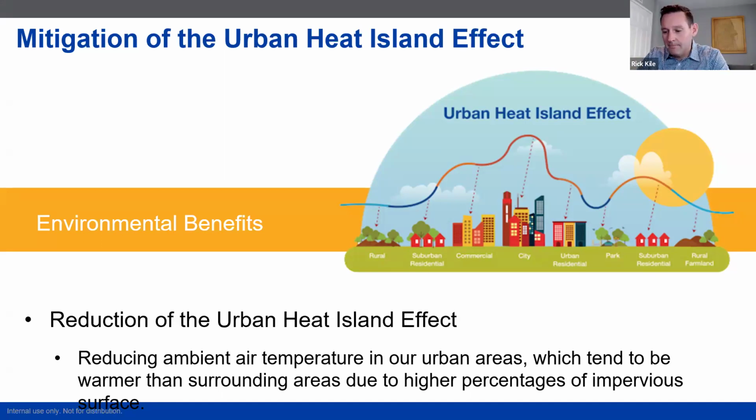I think the most prevalent of those is cool roof technology, or white roofs. Depolluting is maybe a little less known, but certainly a great technology as well. I would say vegetated roofs are a different tool, and I would call attention to the temperature at the surface.